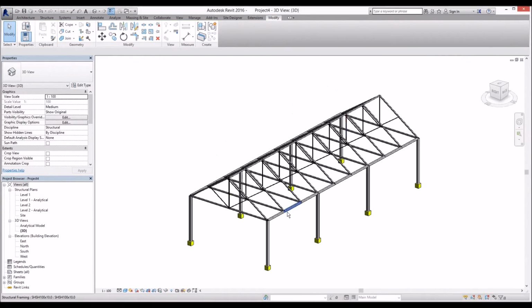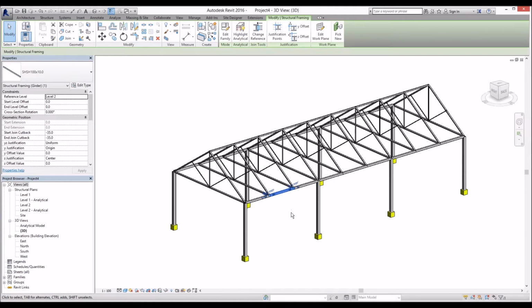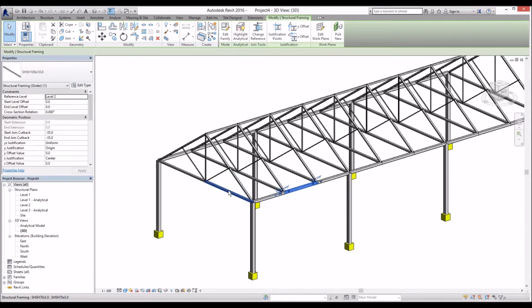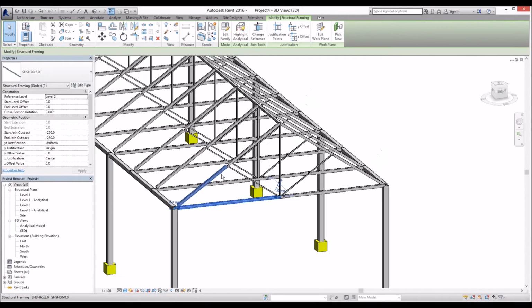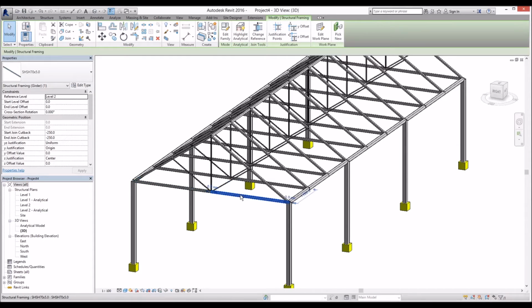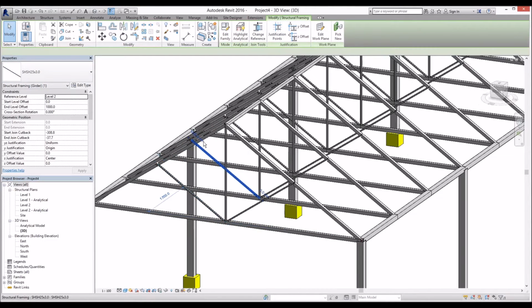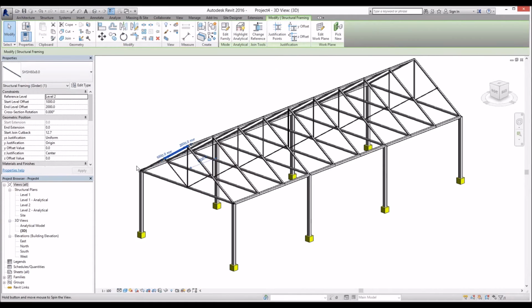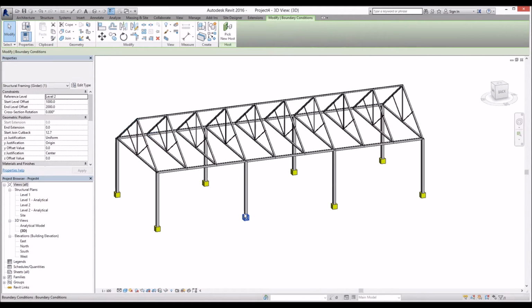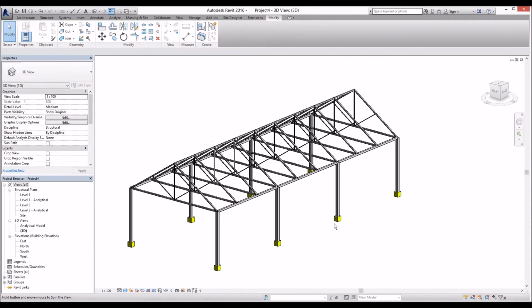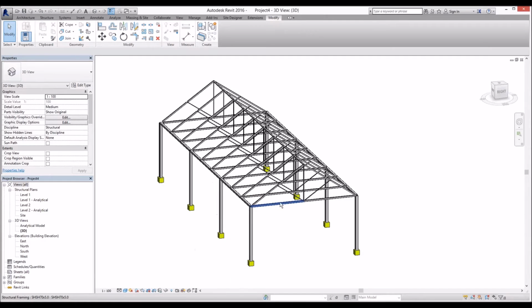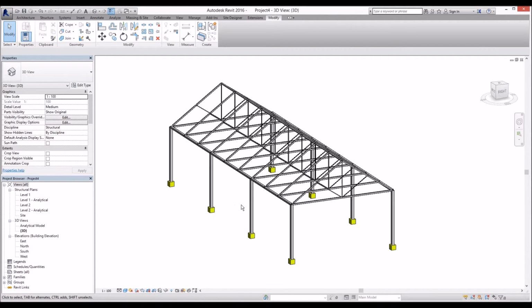So by using the Geometry Gym IFC exporter from Karamba, there is still a little bit of work to organize your structural model in Revit, but still it's quite a good workflow that it generates all these cross section members automatically by simply clicking one button, and also we can get these support conditions to send to Robot Structural Analysis or Tekla, and Advance Steel, etc.